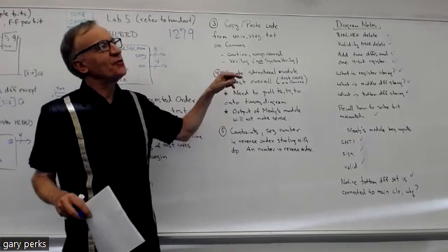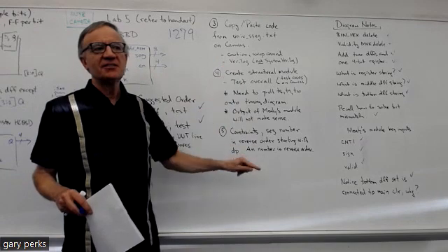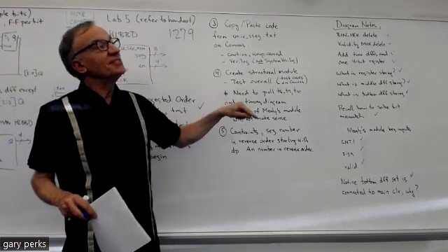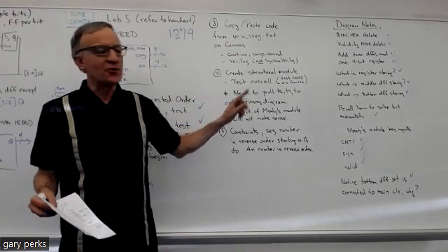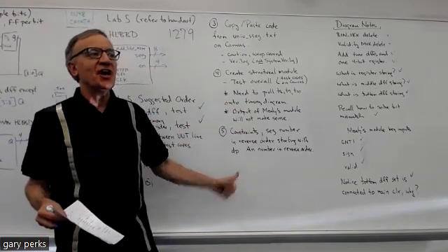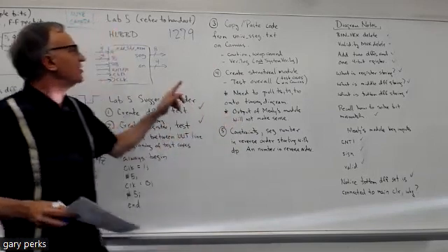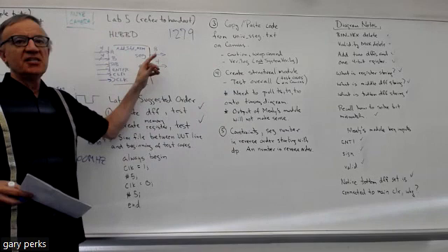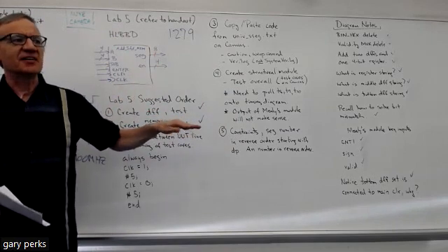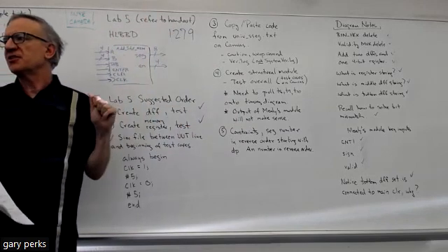Now I can't remember, in lab 4, does it go 0 to 7 and 0 to 3, I think? I think it goes 0 to 6 because you had 7 segments in lab 4, and then 0 to 3 because you got 4 AN. Okay, so if it's like that, you just go the opposite direction in lab 5. Okay, and also remember, seg is now 8 bits, so you would include the decimal point. I think the decimal point is 0, then it goes 1, 2, 3, 4, 5, 6, 7. The opposite direction of what you did in lab 4.